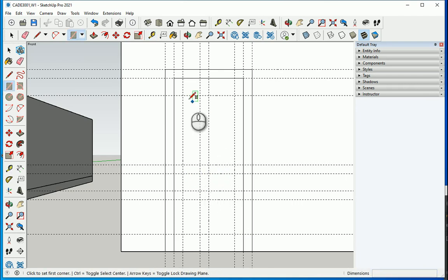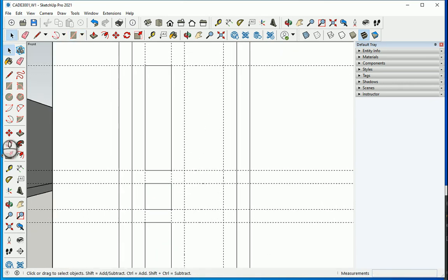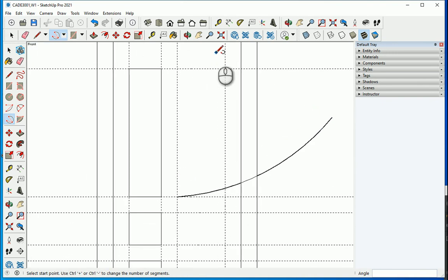So I want to draw some rectangles here, one in here, one here, and one here. On this side I'm going to have an arc, so let's go with a 3-point arc here, here, and maybe like this. So this is the bottom of this pattern. L for line, and I'm going to draw some lines here,